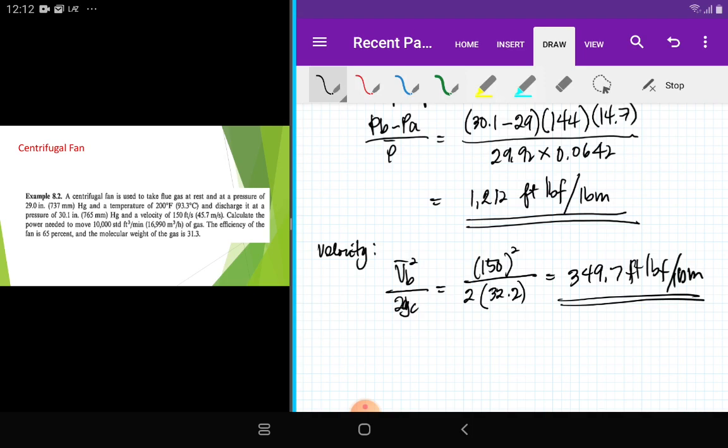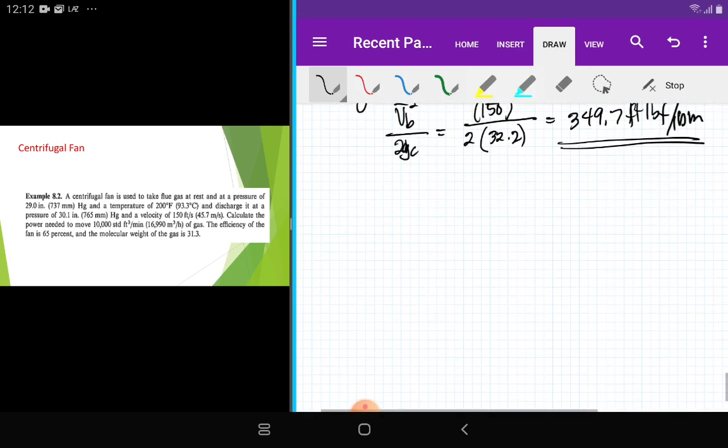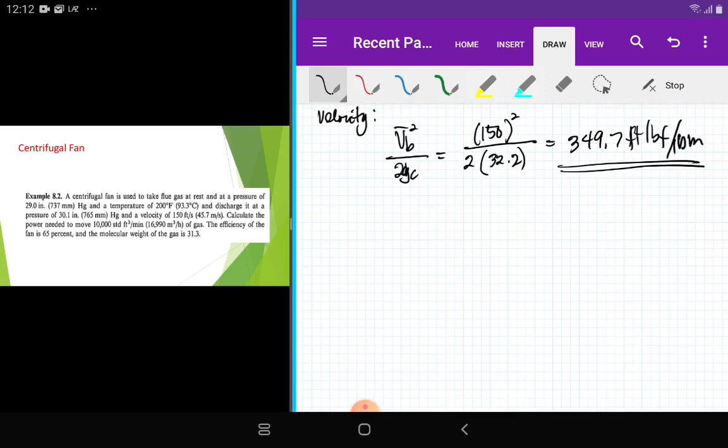Using, of course, the formula for the Bernoulli's equation, assuming that friction losses don't affect the system. Why? Because the system in focus is very short. Therefore, our equation will be shaft torque is equivalent to delta P over density plus delta V squared all over 2gc, assuming that your initial velocity is 0 and there's no elevation, so your potential head is also 0, and assuming that the flow is turbulent, therefore the value of your alpha or the correction factor for the velocity is also equivalent to 1.